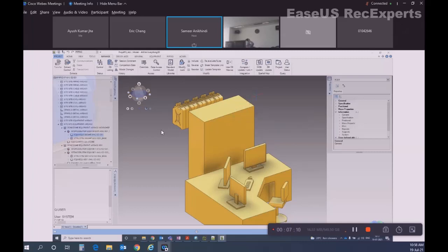Okay, there's another command called DI. DI is for measurement of distance. You can see if I press DI, it will ask me to specify the first point, the coordinate of the first point. You can either directly enter coordinate like this, or you can snap some point. So it has picked already some point. Okay. If you want to come out of the command, use escape. Let me pick the point. So I've used DI. DI is for distance.